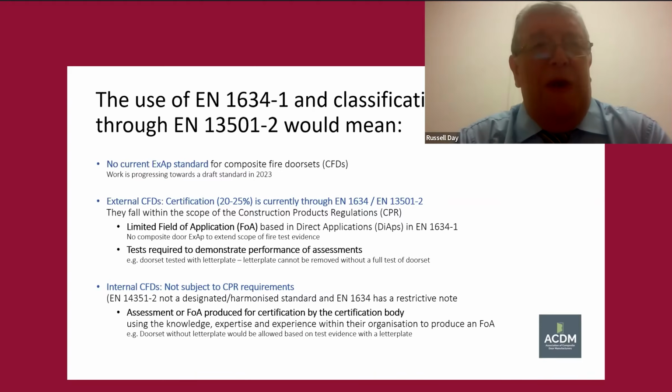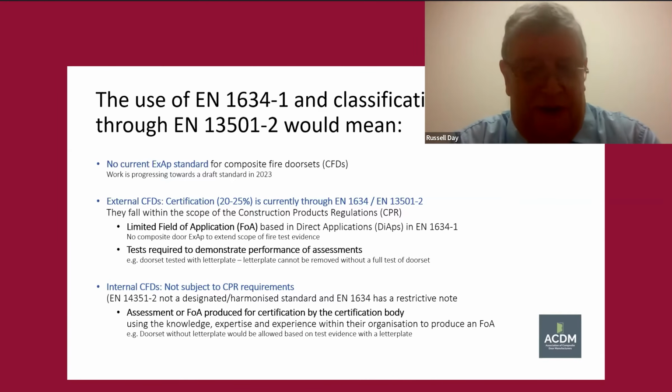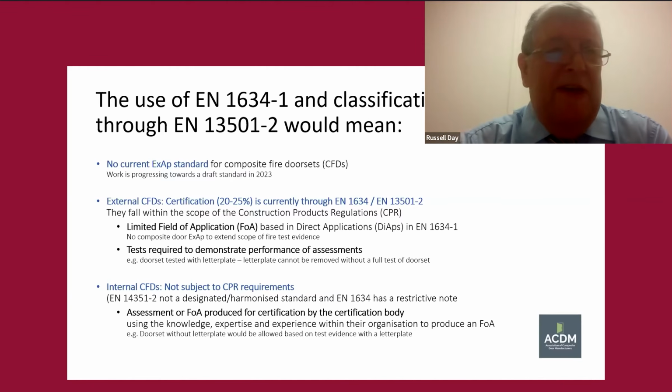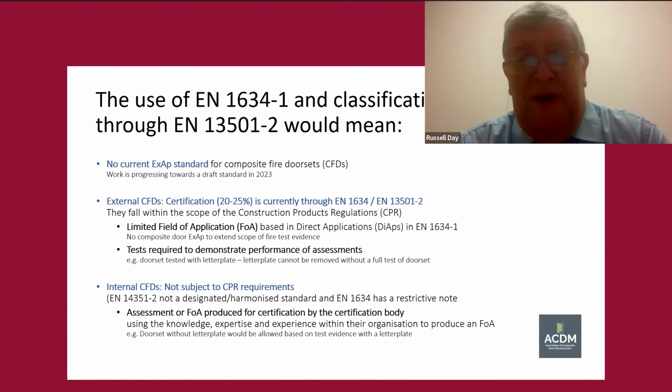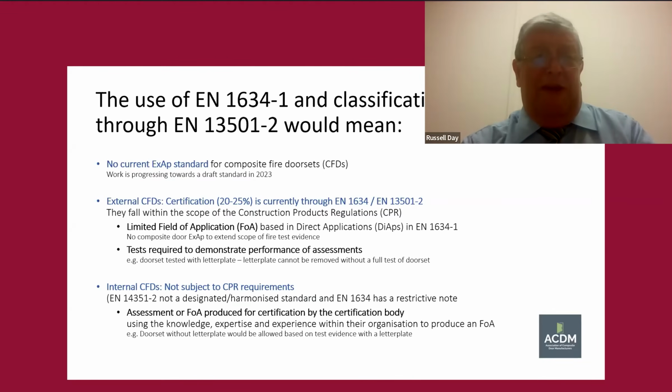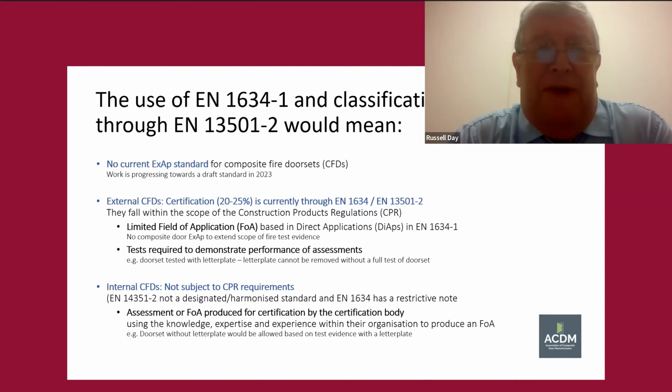So one of our issues when we're looking at changing over to EN 1634 Part 1 as our fire resistance testing and 1634 Part 3 for our smoke control is that there currently is no EXAP, extended application standard, for composite fire doors.